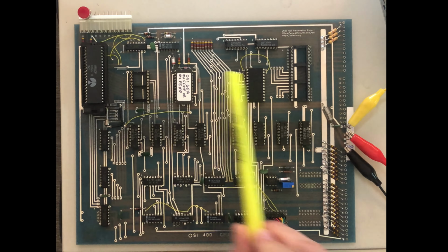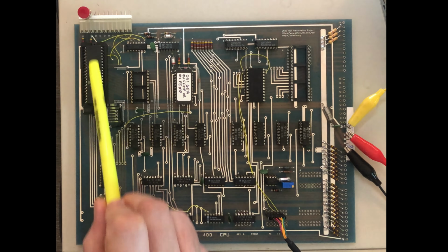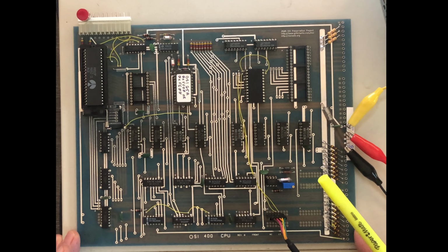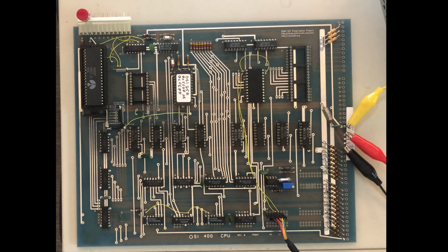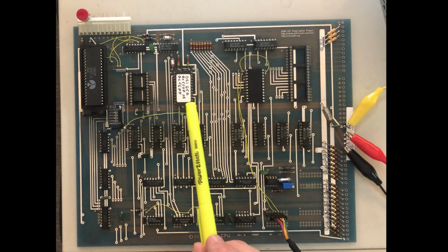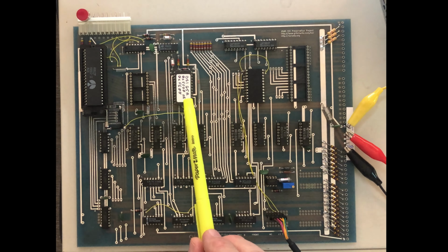So the board has been configured for a Motorola 6800, which requires a two-phase clock and particular connections for the processor here. The MOS 6501 shares that same pin out, and that's why it's configured for a 6800. However, we're going to run, like I say, a MOS CPU in here. So we have the OSI 65A monitor ROM in place here, and that is a monitor for a 6502 processor.